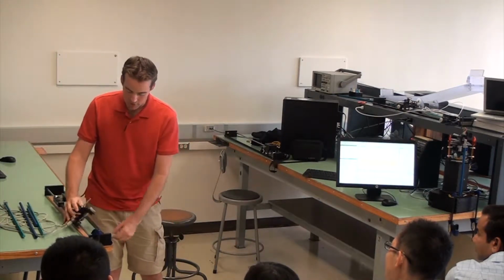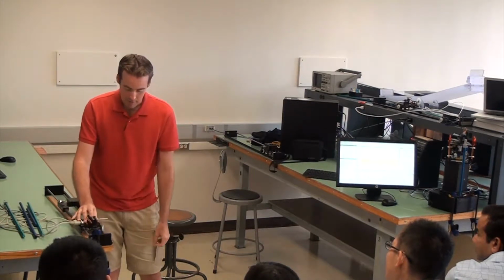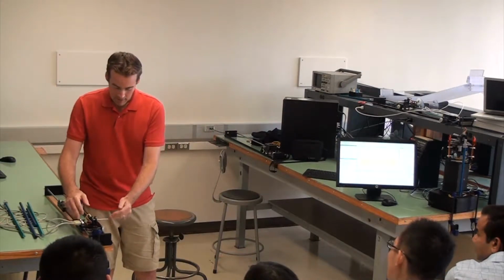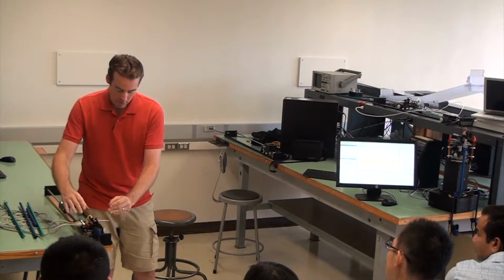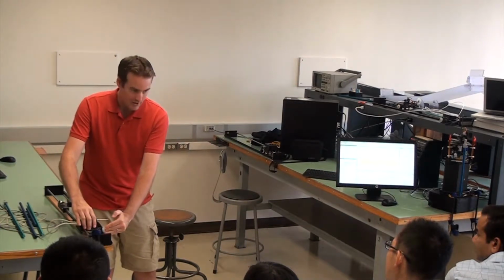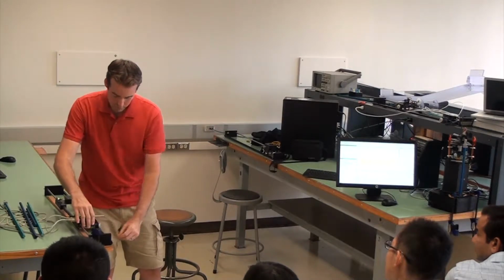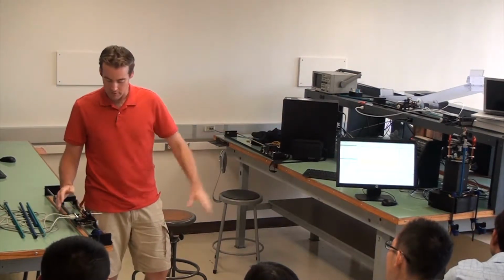Does that make sense? So you have one actuator, the motor, and one sensor, the rotary encoder, and from there you can design a controller very much like the cruise controller that we were seeing. If you want it to be at the 1 foot position, and you're only at the 2-inch position, you can take the difference between those two, apply some voltage, and that voltage will drive the cart over. So you can use the same math from the cruise controller on the cart.